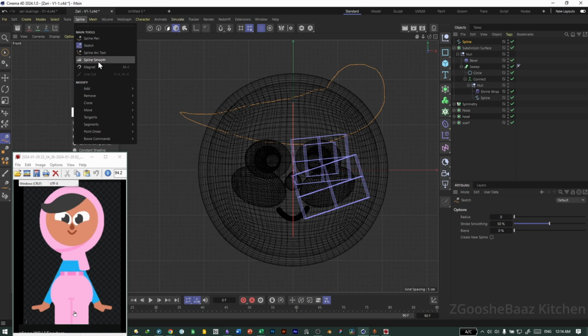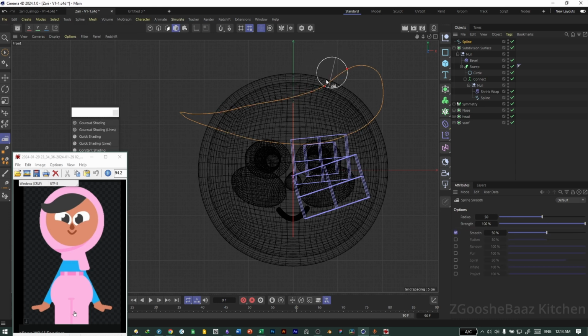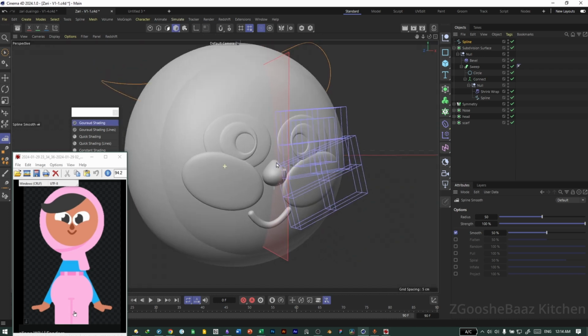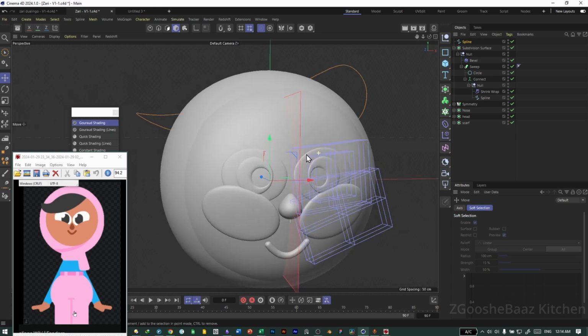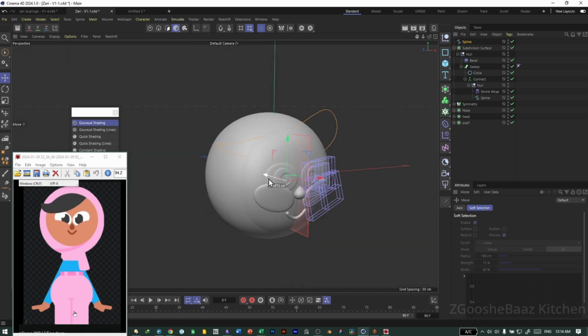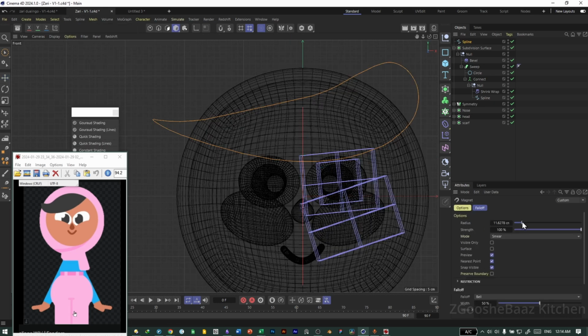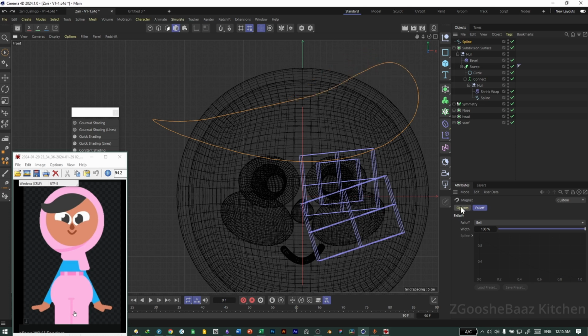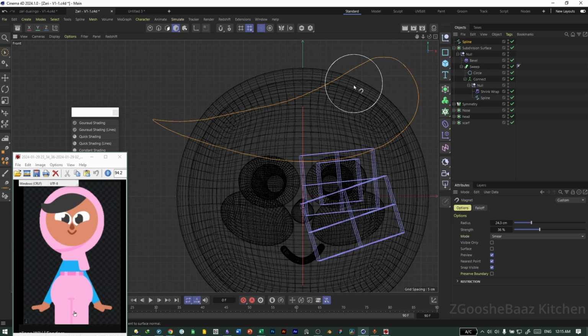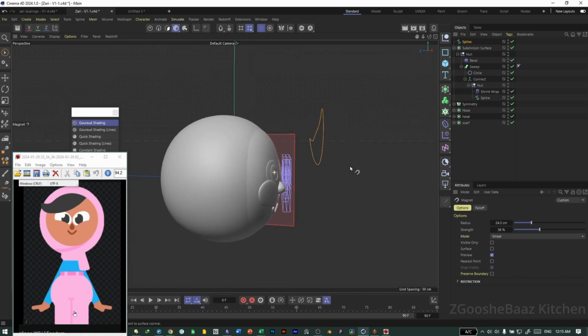Okay. Come here, spline smooth, and move it along the spline by clicking to make it smoother with fewer points on it. As I mentioned, we discussed all these tools about the splines in our spline video. Okay, grab it, push it forward, come back to spline tool, magnet, make it bigger, increase the falloff width, I don't like what's happening. Decrease the strength a little bit. I also turned off the snap visible. Okay, this is good for now.